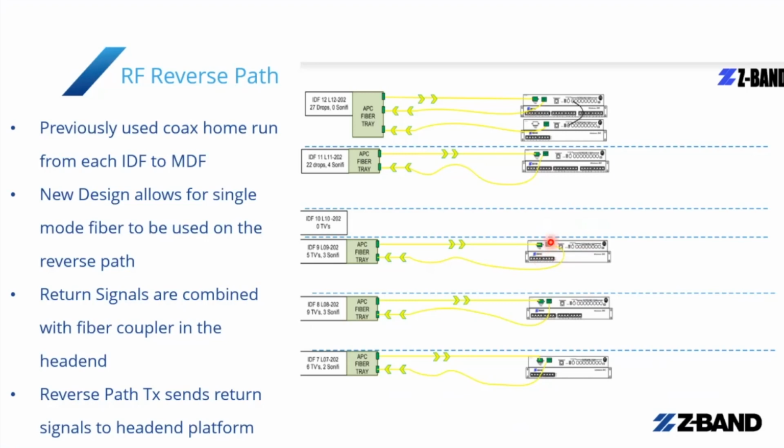The new generation actually embeds an internal fiber transmitter into the rear panel of the ZHC and sends that sub-channel communications frequency through a single strand of single mode fiber all the way back to the head end. So this moves us, number one, from pulling additional coax to now being in the world of fiber. It embeds the fiber transmitter in the ZHC, so it takes away external devices that we need to worry about in the rack, and it moves us to single mode fiber from a communication standpoint, which is great because fiber is the direction that a lot of our clients are going anyway.